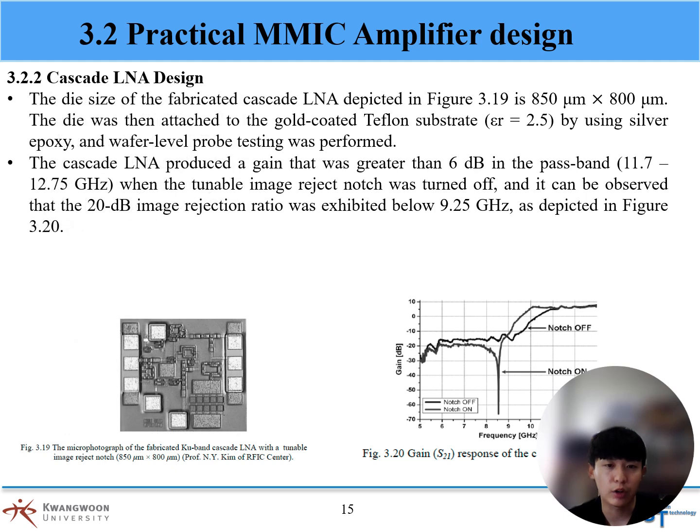The die size of the fabricated cascode LNA depicted in Figure 3.19 is 850 micrometers multiplied by 800 micrometers. The die was then attached to the gold-coated Teflon substrate by using silver, and wafer-level probe testing was performed.